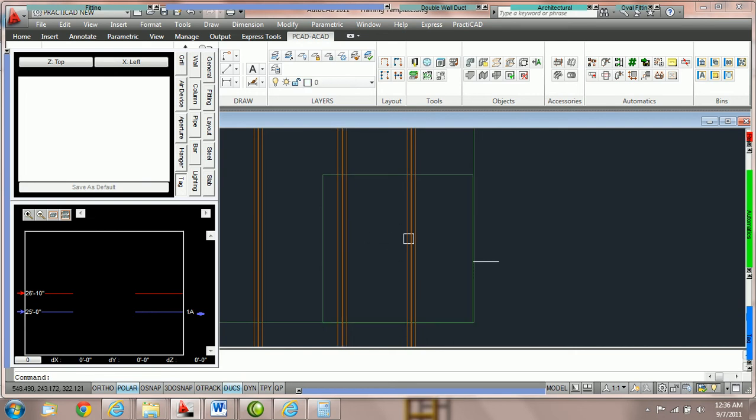And then what we're going to do is click on the steel, and you can see we've got steel beams here, and the bottom of steel is at 35 foot in absolute elevation. We're going to set bottom of steel as the new relative top for our drawing. In other words, our workspace is going to be top of slab to bottom of steel.